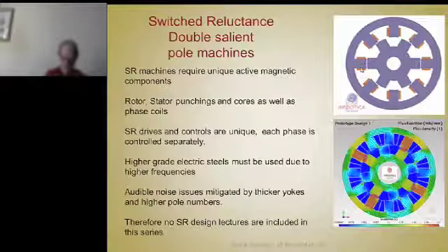Some early proponents of these machines said the rotors are cool, that they don't generate heat. That's not really true. They do generate heat due to eddy current and hysteresis losses, because as you rotate this and attract those poles, you're magnetizing and demagnetizing those poles, and you're actually even reversing the polarity of the poles as you switch and go around. Not on every switch, but at least once per revolution, you're reversing the polarity. So that causes hysteresis losses.